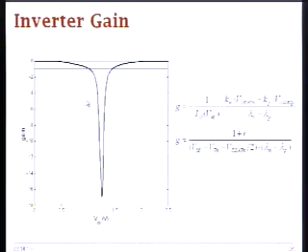What's interesting about this is that digital circuit operation is at either Vin equal to 0 or Vin equal to VDD. That's where we define our logic levels. That's where we want our gates to operate. And analog designers would like their gates to be exactly in this region. So it's kind of like you are either an analog or a digital designer if you look at this curve. So you have digital, a little bit of analog region, and then again you go to digital levels. But it's important to have a very high gain.